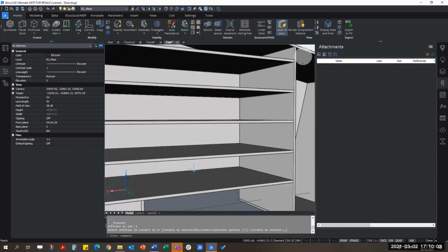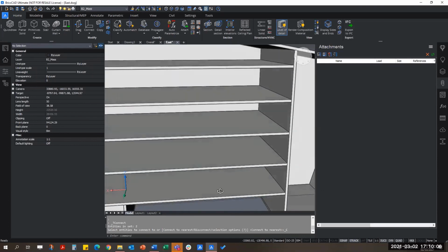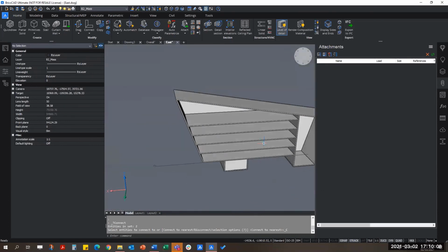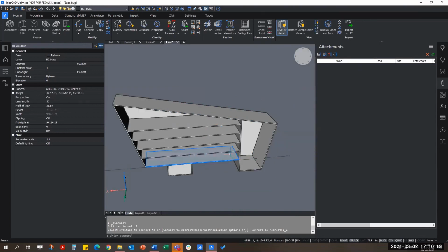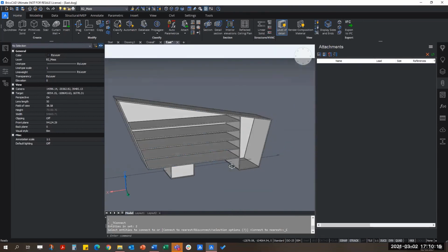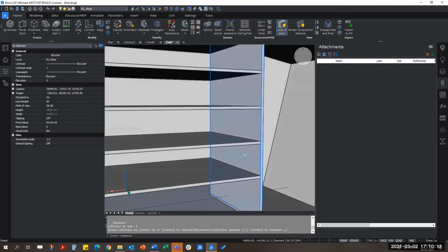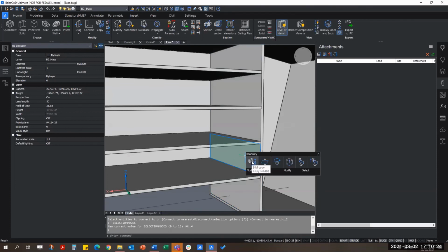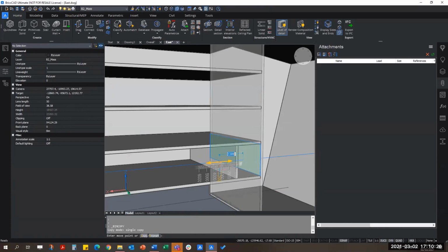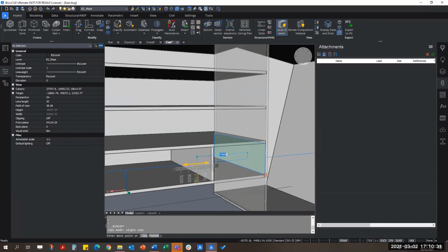And let's say I'd like to bring some internal walls in, but I'm not ready to bring a plan view or plan section, as we call it, through this floor plate in order to model that wall. So what you could do here is you can turn on boundary, select this guy, do a BIM copy, and you notice because I've just selected this boundary here, I'm only given this option to do it just on this floor and not the floor above or below.